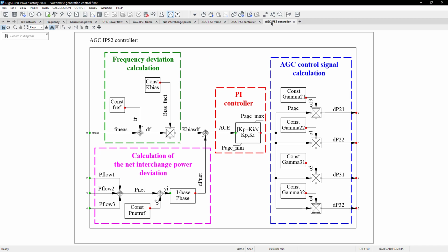And finally, here we have the brain of the AGC controller, because when we have the full PI controller creating the reference, those references must be sent back to the generation unit in order to increase the generation and recover the frequency to the rated frequency. Okay? If you are following me, probably you are okay. There are a lot of things behind this. Yes, I'm really proud of Anton and Pavlovsky, because they created a very beautiful model.